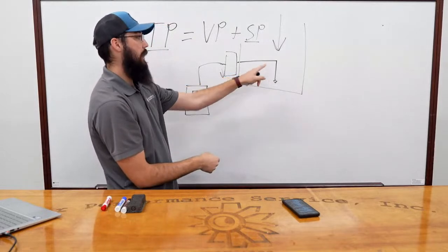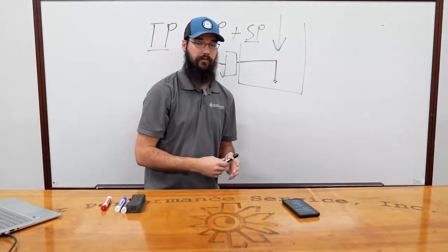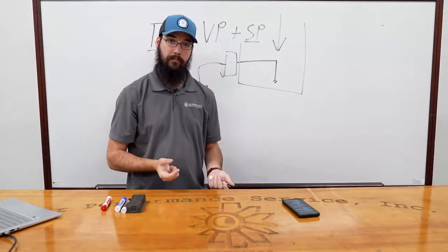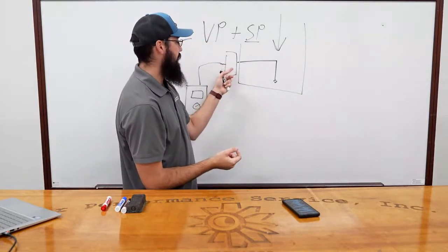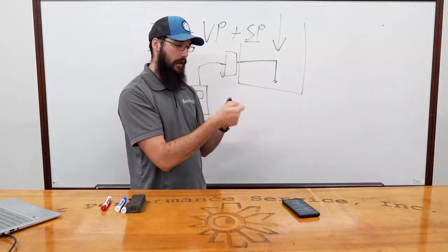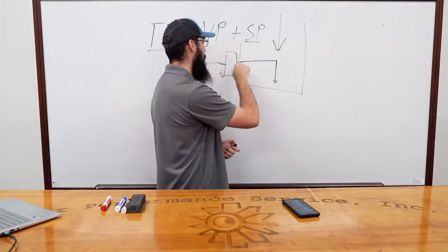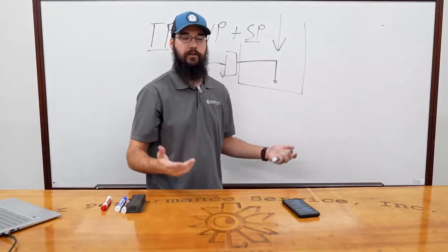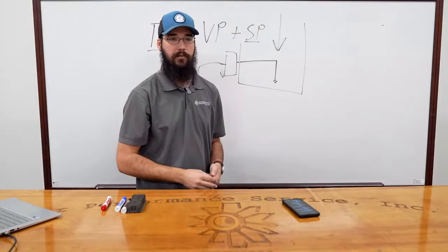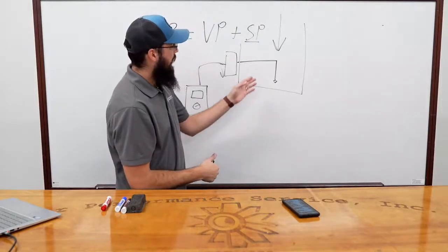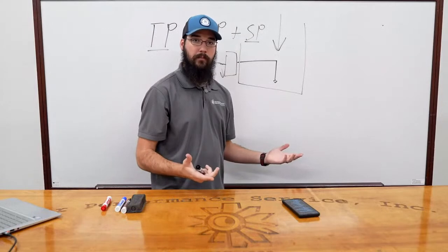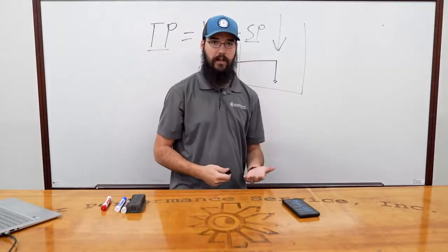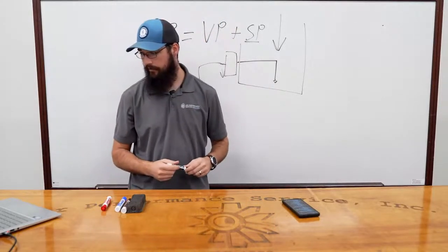I actually made my own of these. My very first, actually I still use them, to be honest. I just took some 1/4-inch aluminum tubing, and I don't have a magnet or anything, so I have to hold it by hand, and I know my tools, so I know how to use it, but I just put a 90-degree bend in some 1/4-inch aluminum tubing. I picked it up off of a job site. It was just some scrap laying on the floor, and I turned that into pickup tubes. And so that's what I use. You don't have to spend money if you ain't got money in order to take these measurements. You can create this stuff yourself.